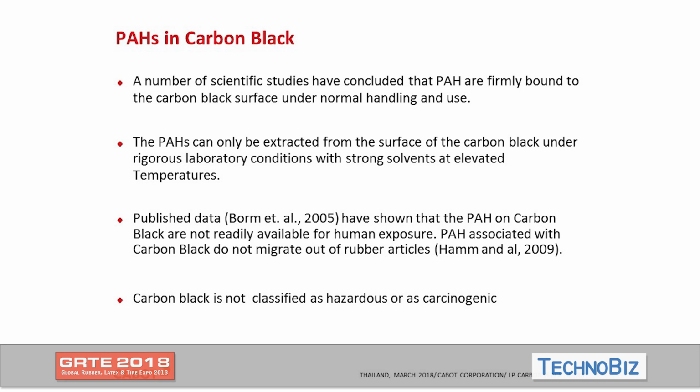Generally speaking, from the toxicological analysis, carbon black is very close to coffee beans. So from that point of view, carbon black is quite a safe material. However, as I mentioned, all of the regulations talk about the PAH content in the end articles. So as part of the compound, it's necessary to show what the PAH content in carbon black is. This is quite an important topic.